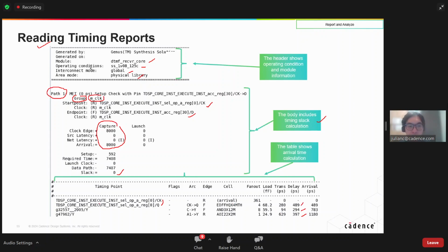So this one is the name of the instances. These are your logic gates. So is this a synthesis generic or synthesis mapped netlist? This is a mapped netlist because it has already been mapped to a library instance, library cell. So this is an AND gate, this is an AOI gate, maybe it's an AND/OR gate or something.